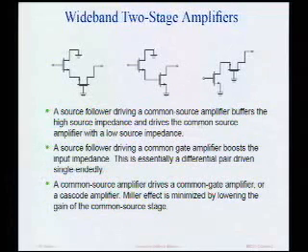And the way I fix my problem is, you might say, well, you still have a Miller capacitance here, but I've reduced the voltage gain on the first stage, right? What's the voltage gain of the first stage? Yeah, 1 if the devices are sized equally, -1 to be more exact. So the Miller multiplier factor is only 2, right? So the capacitance doubles, which is not too bad, as opposed to getting 10 times bigger in the common source amplifier.